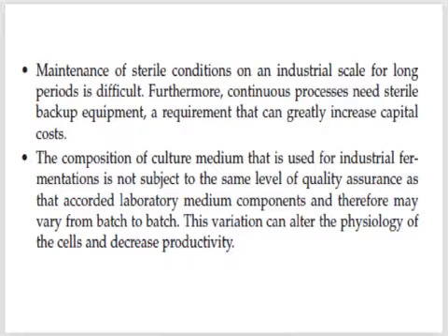It's normal, right? Because the characteristics of the raw material, the substrate or the media that you use in your fermenter, depend on the quality of the raw material. So if the quality of the raw materials varies, eventually the quality of the media that you use in the main fermenter will also vary. So you can get a product with different quality than the product that you get in the laboratory, and there is also a chance that you will get less product in your final fermenter in comparison with the amount of product that you get during your laboratory experiments. So these points are important.